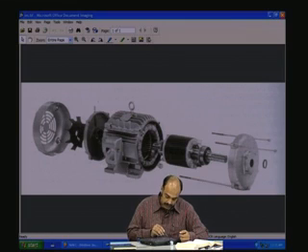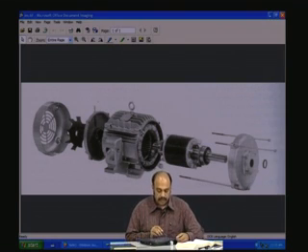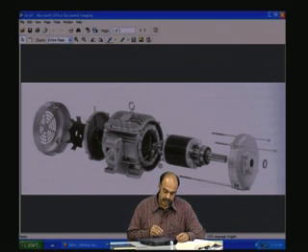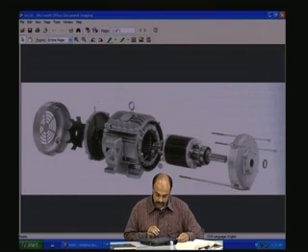Beyond this face plate there is something mounted on the shaft, and that is a fan, and beyond that there is another enclosure, a covering for the fan. This fan provides cooling for the machine, that is, this is an enclosed air cooled induction machine. So this is how the various parts of the induction motor look.